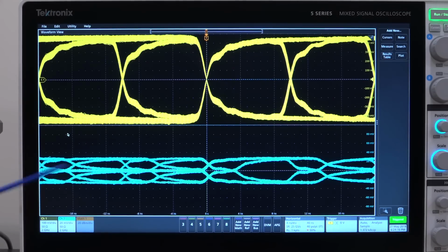So now if you look at the bottom, it looks kind of pretty, and that's because it's essentially a derivative of the top eye diagram, and it has various transitions depending on how the PRBS is transitioning and how many ones and zeros are in your row, and the frequency content of it is determined by that. So what if I want to reduce the crosstalk at the bottom? What can I do to do that?